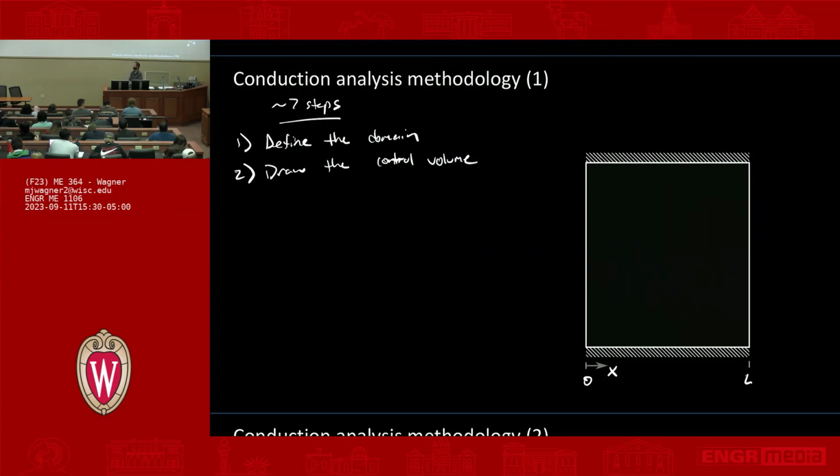It's differentially small. And we have to be careful that we're only showing depth in the direction in which temperature is changing. You don't need to have a differential element that has depth in any other dimension other than the one that's changing. So for this problem, you could draw it like this, but don't draw this.